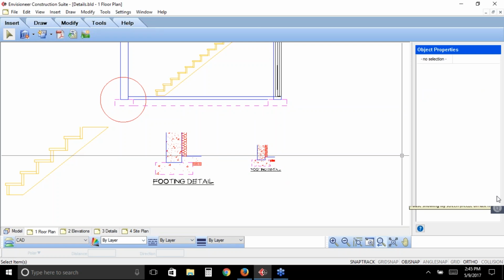Okay, and let me go to our next question. I noticed CADSoft has a lot of details. I used a few in whole, but can I adjust or edit any of these details? Absolutely. Any of those details that are in that list, bring them in, modify them as you need to, and then if you export them and save them as the exact same name, it'll overwrite the existing drawing file so that you're using your new ones that you want to. So absolutely, bring in any of the details that you saw in that list, and you can edit any of them.